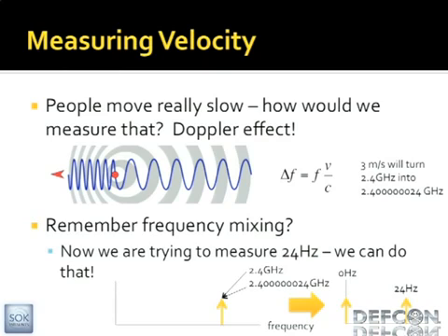So if we send a radar pulse, like what I'm calling a continuous wave tone, which is just a sine wave, at something that's moving towards you, when it reflects that, it's going to increase the frequency because it's moving faster. It's not going to change the propagation speed because everything moves at the speed of light, due to relativity. But it's going to compress it in space, rather, so it's going to increase the frequency of the signal.